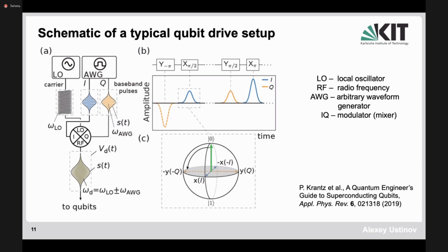So it shifts in frequency relative from 0, now the 0 becomes the local oscillator frequency. And in that frequency range, one can basically manipulate the signals. It will be ideal, of course, if we can directly digitize the signals, generate the signals directly, but semiconductor electronics is not that fast yet, and it may occur in 6G, but didn't occur yet in 5G.